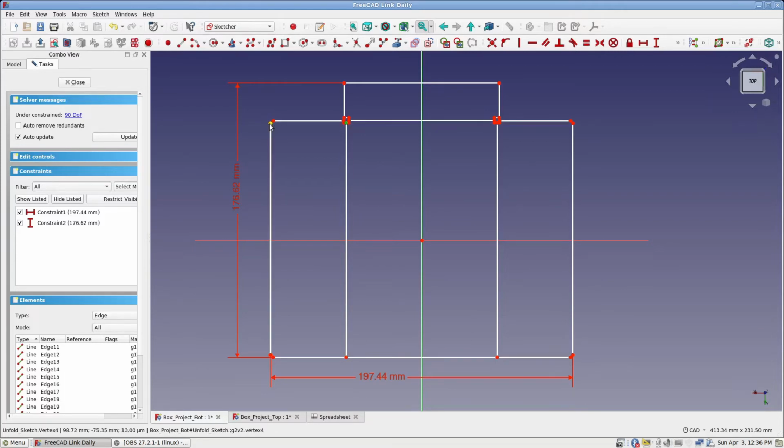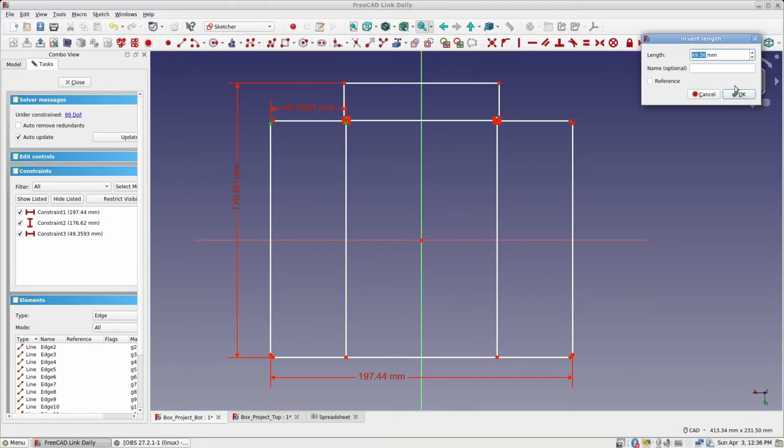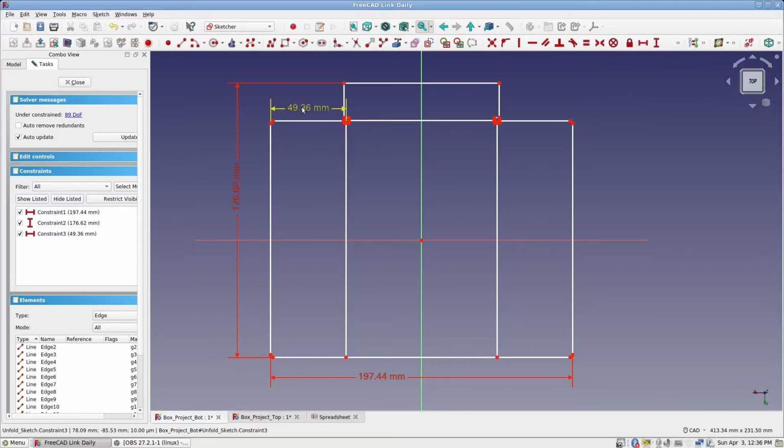We've got to pick this point. When you bend this in a press brake, you're going to register this edge against the back gauge, and then your die is going to come down on this bend center. So let's do a horizontal constraint there, and click OK. So there's your bend line. This part is symmetric about its center, so this side here is the same dimension, so we won't bother with that.